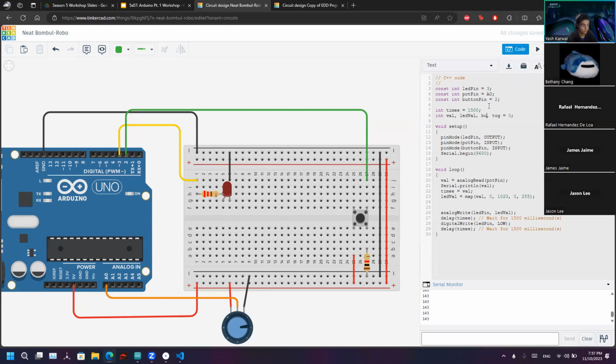We're going to view T val, not val. That way we know what it is. Okay, so we use input pull-ups for when our default state is going to be a high. So if instead of pin 2 being on terminal 2 on this side where the resistor is, this was actually on this side where 5 volts is the default state, then when you press the button, it's going to go to the ground.